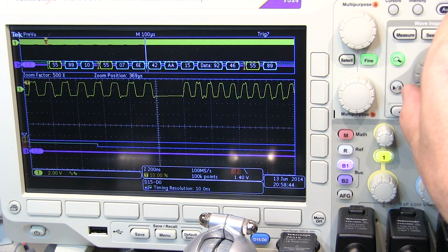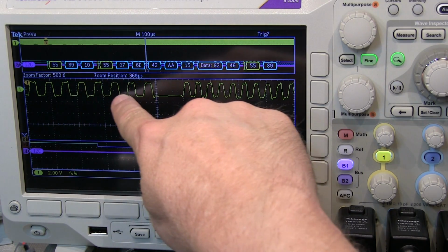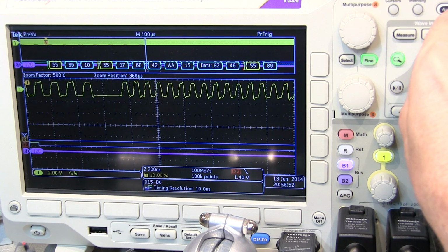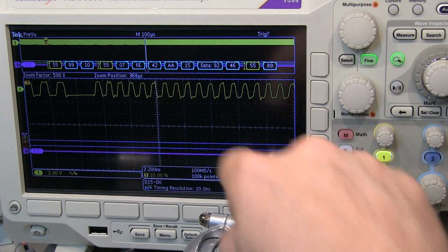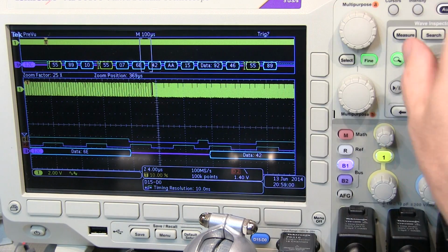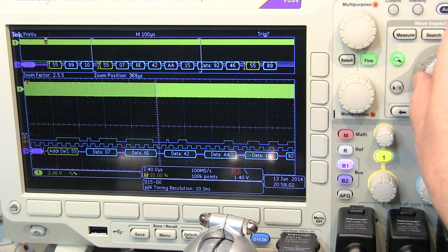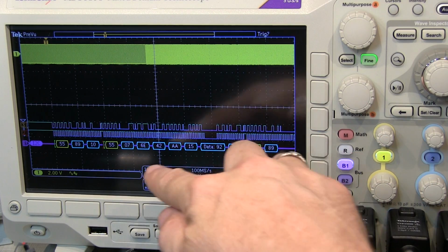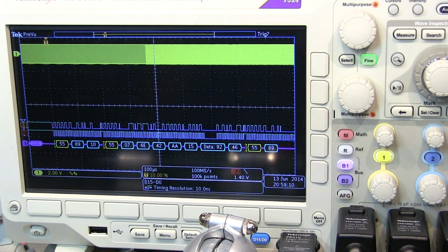Okay, and now very easily we can see the change in frequency from here down, and we'll go the other way to here. We went from a lower frequency to a higher frequency. That was all in response to this bus command telling it to tune to a frequency. Now, of course, the data sheet for the Si570 will have all the details of what registers you need to program to get a given frequency output from that device. But that just shows the cause and effect relationship between the I2C bus and the Si570 output.